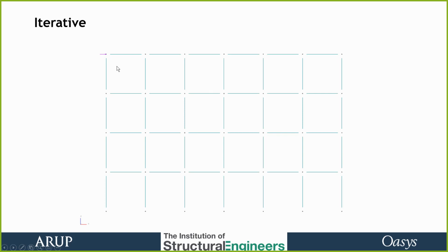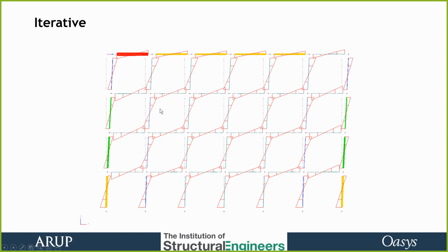We make an initial guess, put all the sections the same size, so all have the same stiffness, and we'll then get this distribution of bending moments and axial forces, which means that if we then design this, the columns will get a higher load, they'll end up getting stiffer. So they'll attract more load, and we'll iterate through.